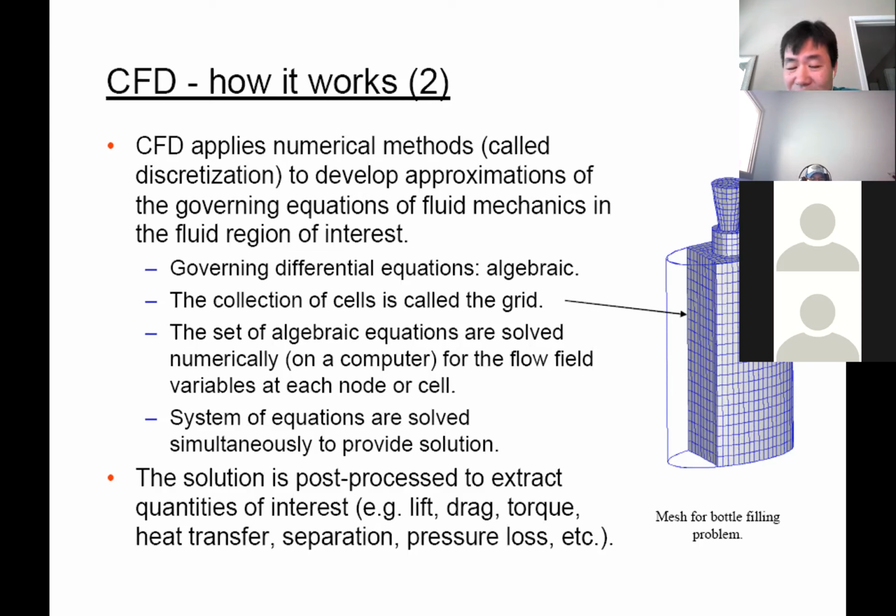Higher values may be red, but lower values are blue. So it shows the distribution of those values on the selected surfaces. But for contours, you need to select a surface. It can only show on a 2D surface.